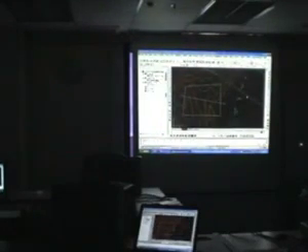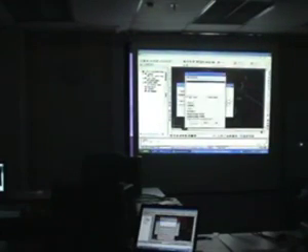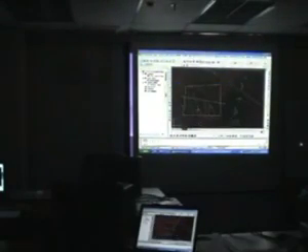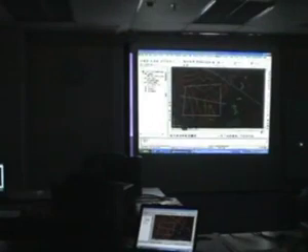First, we need to specify our stratum. We specify which is our original level, so this one, then which is our proposed level, those 2. And then next, we need to define our site, because sometimes we have such a big area, maybe we only want to do the volume calculation for one small area. So this is what the site definition is for. I'm going to specify my base point, which is the lower left corner of the area. Specify your grid size. This depends on your project, of course. Every project has a different grid size. And this is the site which you're going to use.